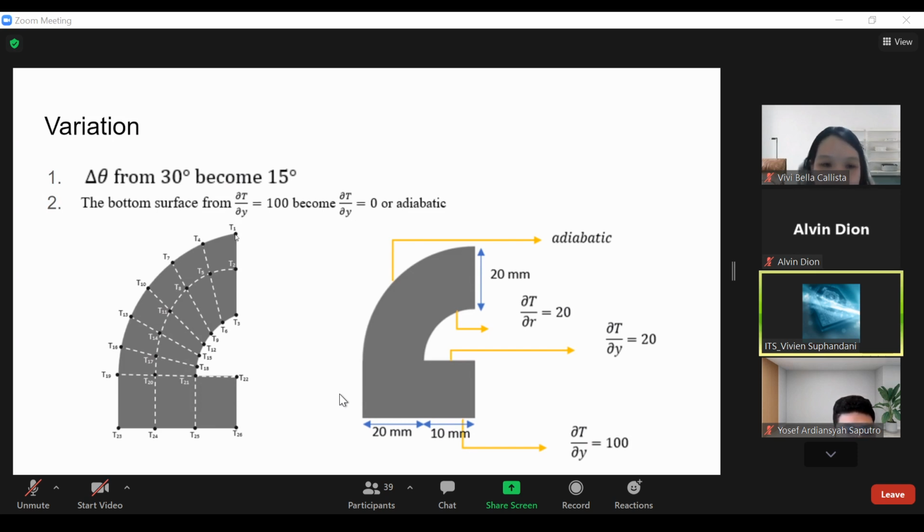One thing to remember is that we are trying to solve a system here. So this is very similar to the first problem from the Sultan group earlier. The problem might be almost similar, but here you have a very negative value. And if you look at the problem, you have a heat flux there, and then you have an adiabatic boundary. This is possible if you use all Neumann boundary conditions and you have specified the gradient there.